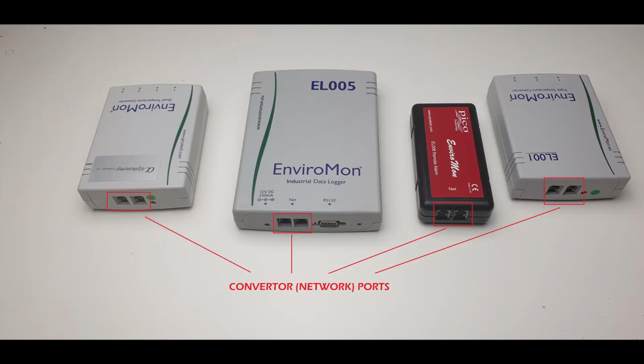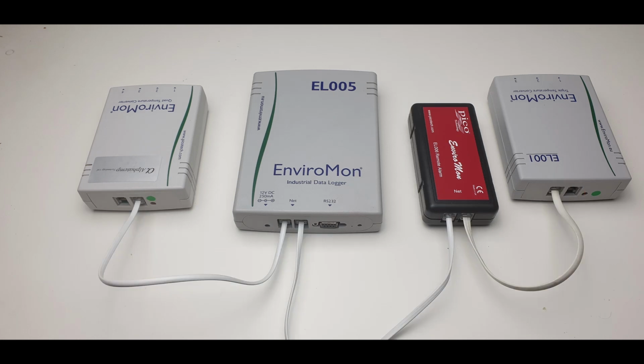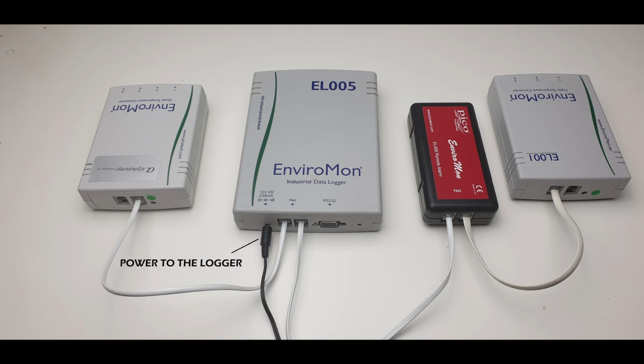So the next thing we'll talk about is the connection interface between the logger, converter and alarm units. Each of these devices has 2 ports, which allows you to daisy chain them together with the logger. Each of these ports provides power and communication, so you only need to power the logger and your converters will be powered by the logger from the converter cable.